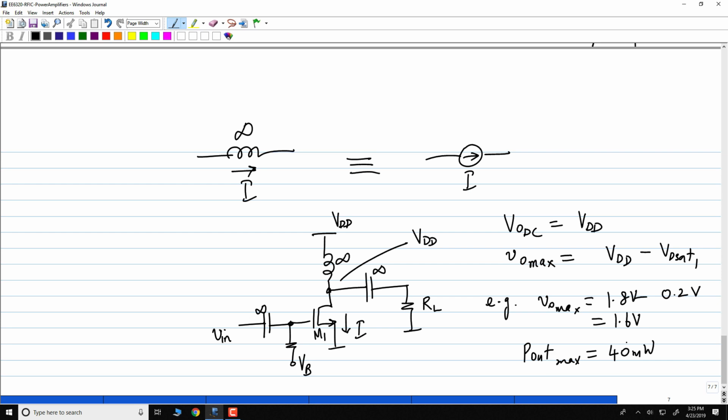Fundamentally, this circuit allows you larger swing, primarily because you have removed the limitation on one side. And more importantly, you are biasing the output at VDD. Okay, so that gives you an extra VDD by 2 swing that you did not have. So fundamentally this circuit is just better. You don't have the parasitics from the PMOS transistor. You only have the parasitics from the NMOS transistor. What is the bandwidth of this circuit? It's also going to be wider. You understand?